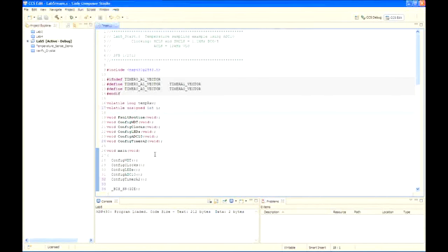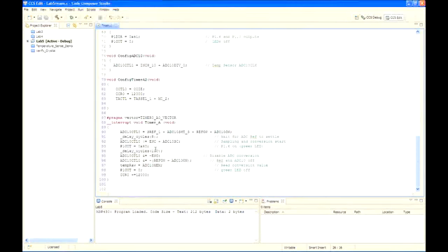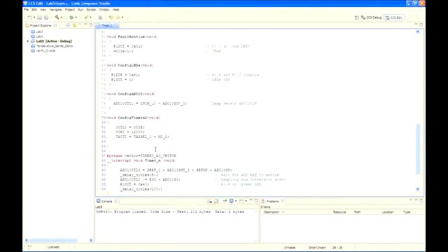As we progress through the labs, what we're trying to do is take you a bit further away from using hex codes and a bit more into using codes that are much more readable. So let's make some changes to the code for readability and for the LED function. Take a look in your fault routine and you'll see P1OUT equals 0x1. We can change that to P1OUT equals BIT0. That's easier to read. In the config LEDs function, you'll see P1DIR, that's the direction register, equals 0x41. Let's change that to P1DIR equals BIT6 and BIT0.